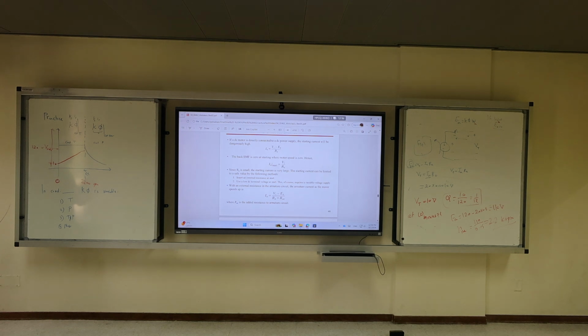Now let's jump to, we finished motor control, and you as an engineer, if I ask you the question, do we love traditional control, power electronics based control, or what? Power electronics, because you can control alpha, you don't have to wait for the load, you can change the voltage, and you don't need a DC supply. Having industrial DC supplies is not practical. And that's why many DC motors run directly on the wall, because they have the converter inside.